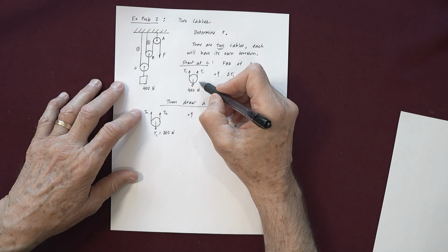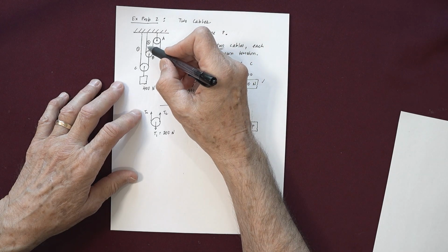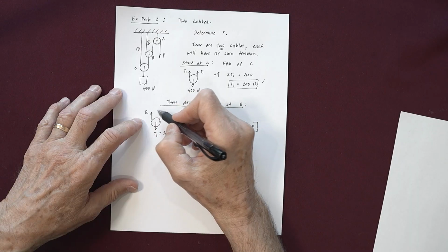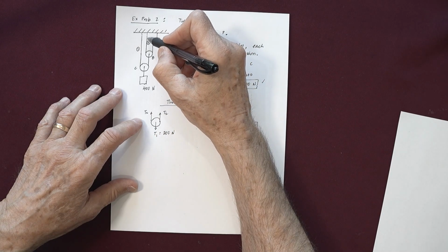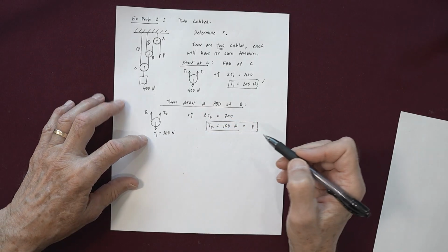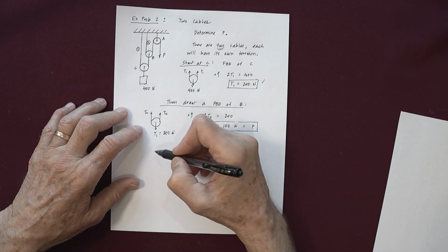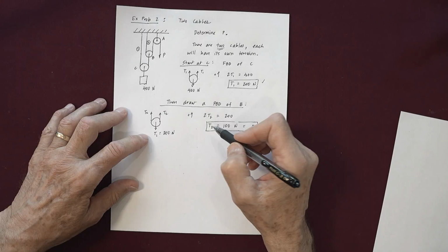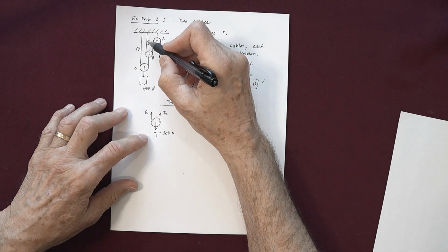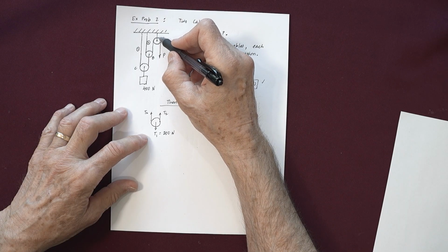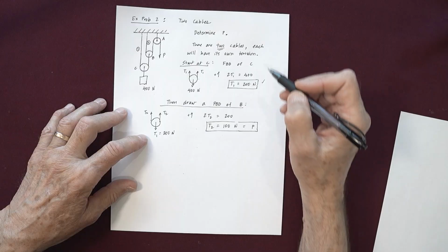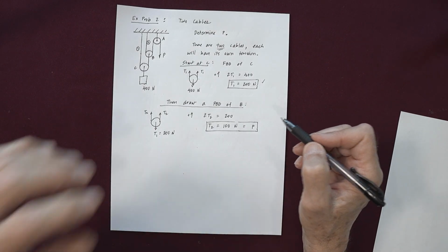Once you get T1 is equal to 200, now we can go up to pulley B and draw a free body diagram of it. You get T2, T2, which is the tension in cable 2. And then you get T1 acting down, which we just found to be 200. If you sum forces in the vertical direction, you get T2 is equal to 100 Newton. And once I get 100 in this cable, the pulley A just changes the direction of cable 2. So P here is also equal to 100, for T2.